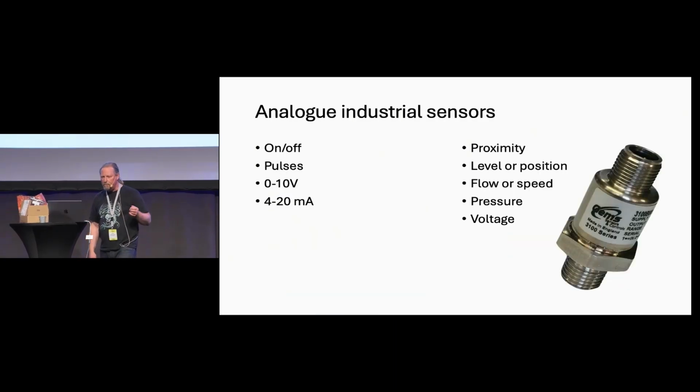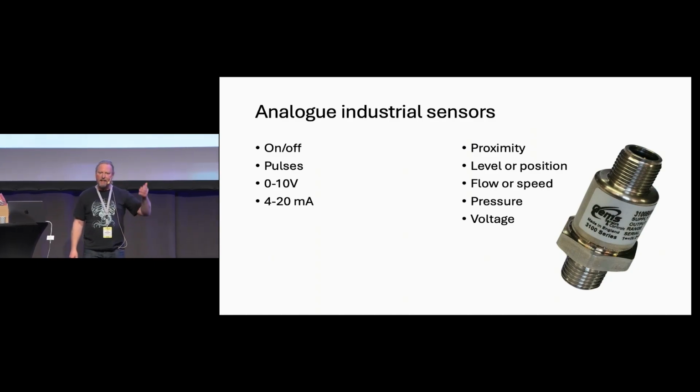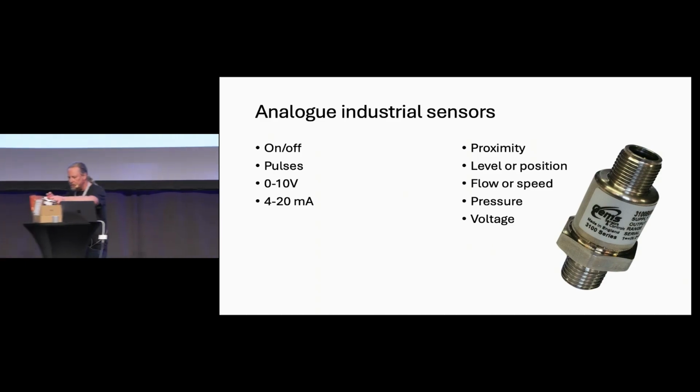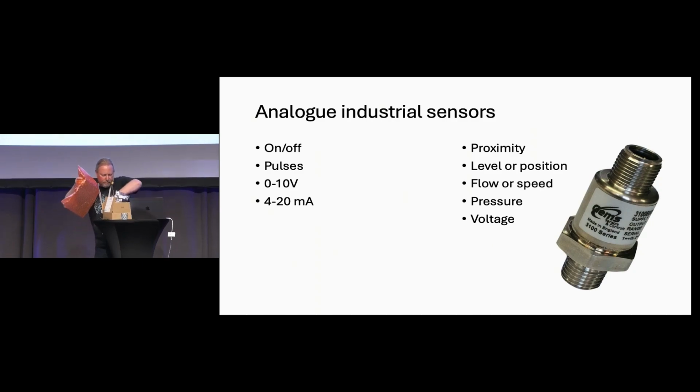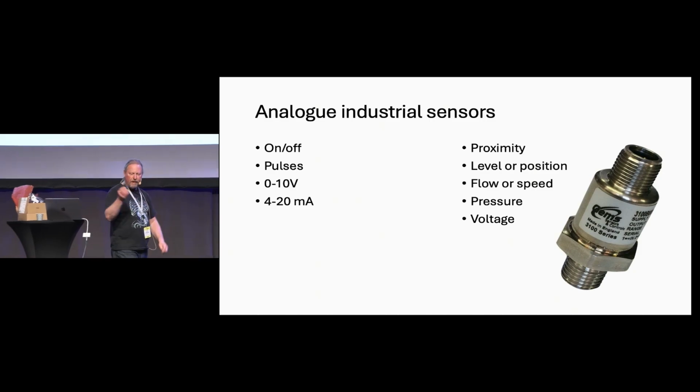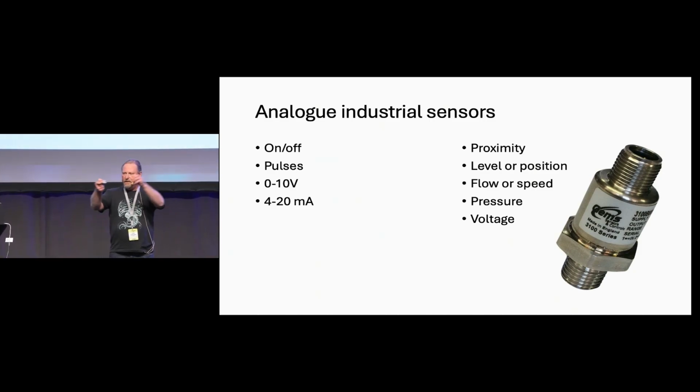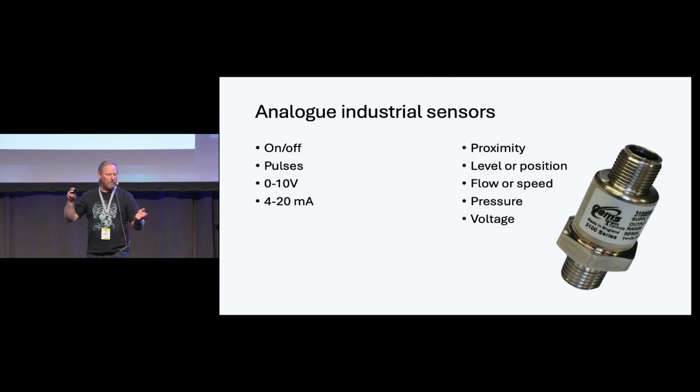That meant I needed to hook up with a lot of industrial sensors, and I did that as well. An industrial sensor can be something like this. This one can measure distance. It is a laser, and then there is a contact. And the typical thing for industrial sensors is they're quite rugged. They run on 24 volts, and you can get the voltage or current signal that is like the level out there. And it's usually between 0 and 10 volts, or you get a current between 4 and 20 milliamps. So it's really easy to interface with those.